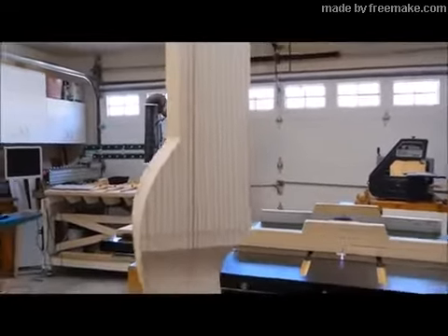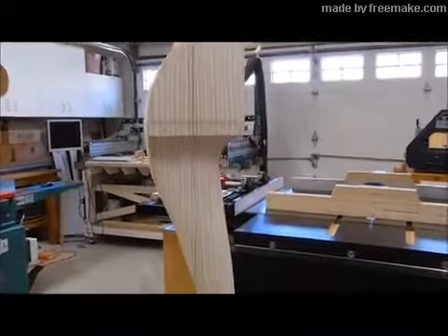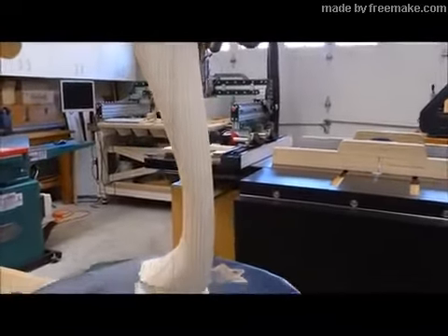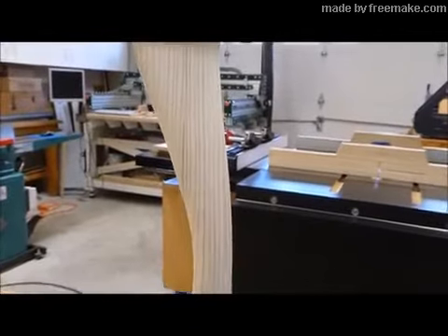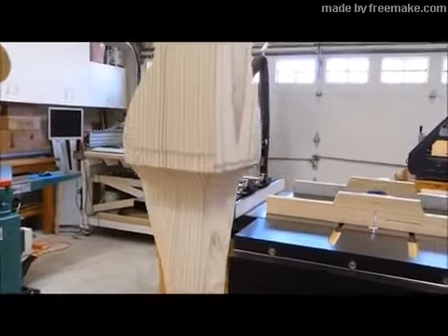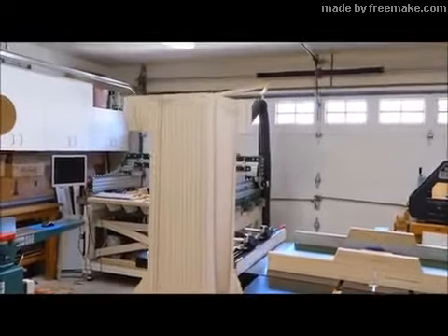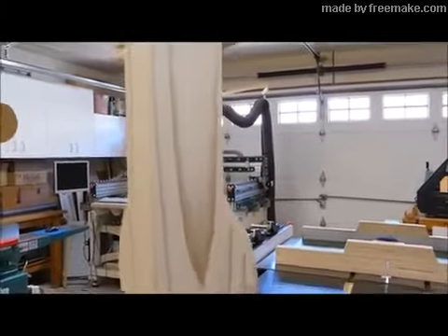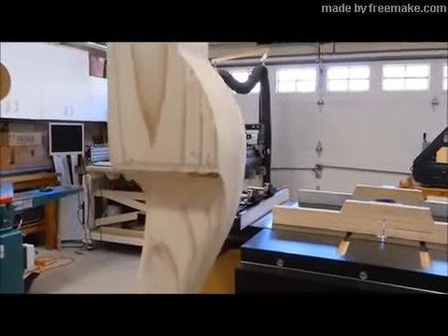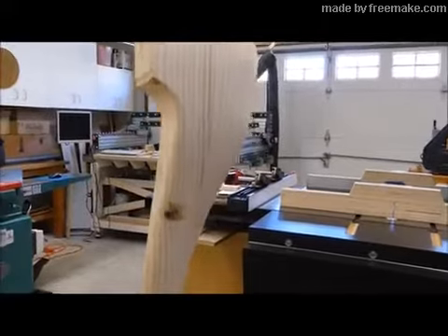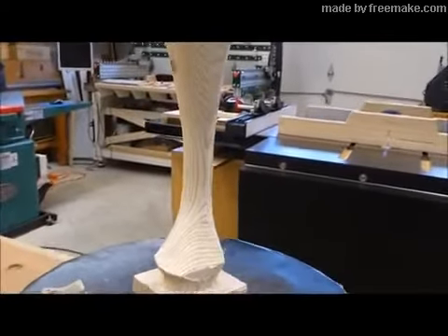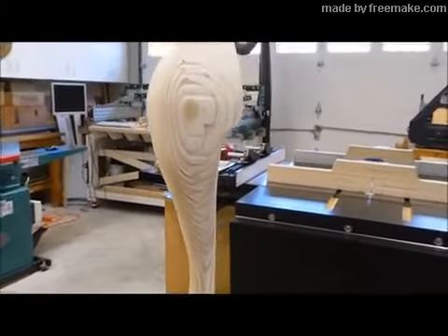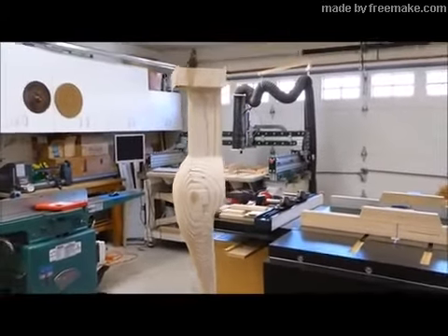Total machining time was 62 minutes. The blocks at the top and bottom, of course, will be cut off. I expect to do this with a sled on a table saw. Handwork with a cabinet scraper and some sanding will be required to remove all tool marks. The tool marks can be lessened with a smaller step over in the finishing pass. In a subsequent experiment, I found that reducing the step over to 0.07 inches greatly reduced tool marks without adding too much to the cutting time.